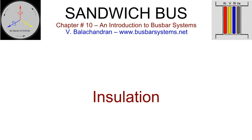It is necessary to have 100% redundancy to ensure that a pinhole in the insulation strip does not compromise the integrity of the insulation. Epoxy can either be coated by electrostatic spray or fluidized bed dip or extruded over the conductor. Epoxy coats are marginally thicker than the mylar insulation. A mylar film can be introduced between the coated bars and earth to provide an additional factor of safety. The gradient of the temperature across the insulation should be kept to a minimum to evacuate the heat more efficiently, thereby increasing the current rating of the busways. Most manufacturers confirm a thermal class F, though class B should suffice for the insulation.